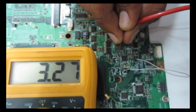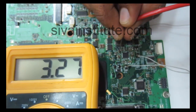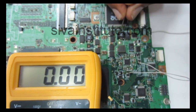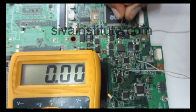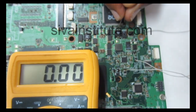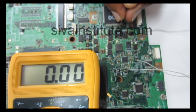You will see here 3.3 volts is okay. We will see at the coil. No voltage at this point. After pressing the power button, this voltage will come. Without pressing the power button, this voltage will not be present. When you press the power button, this voltage will come. Bias and SIO chip is okay.